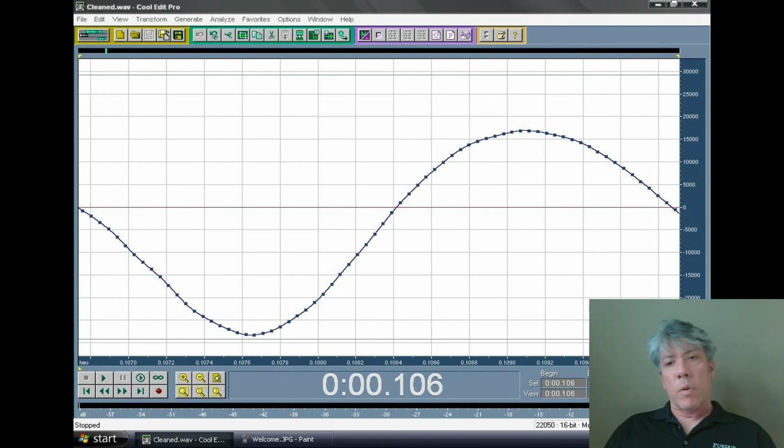But in the analog world, I'm not really aware of any high-speed inputs that automatically track the signal, because really the idea is that the PLC needs to be able to respond to it in real time. Most of the time you're doing PID control or something like that. And we haven't talked about PID control in the class, but that's the control algorithm most commonly used for continuous signals.